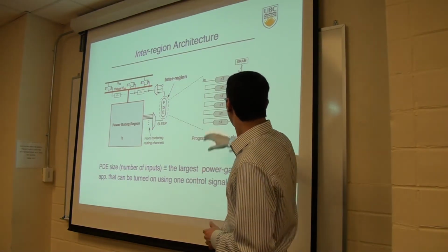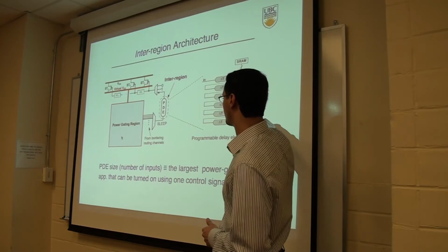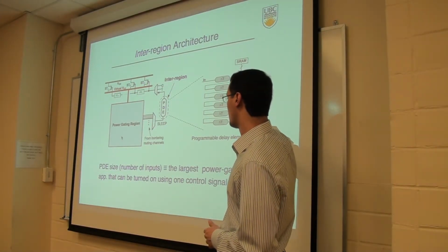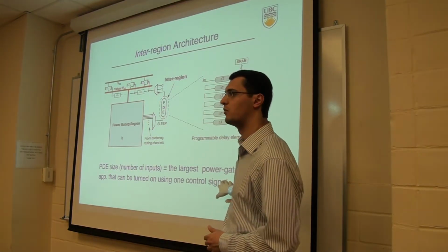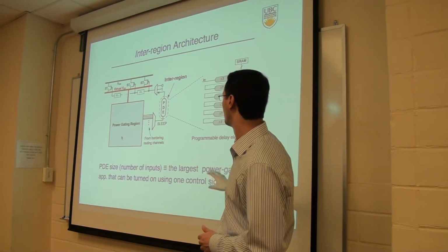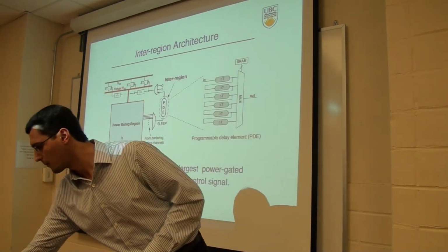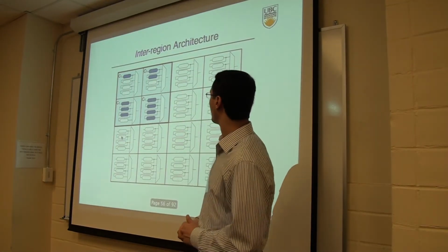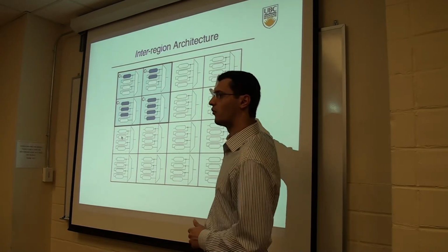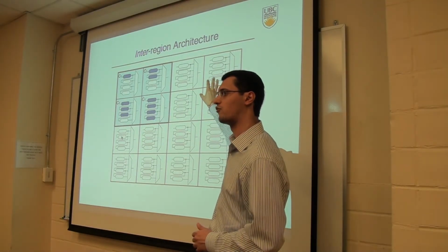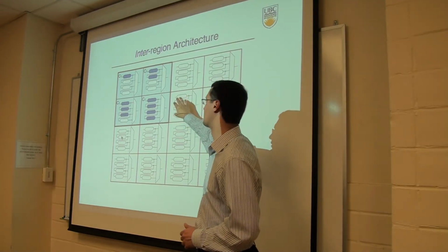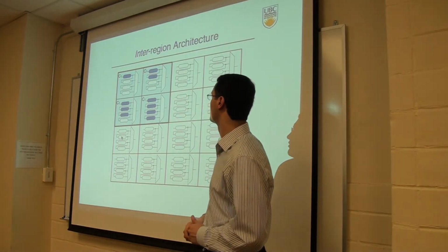One thing here is that the size of this multiplexer, or how many delays can be generated by this programmable delay element, is related to the largest power-gated application that can be power-gated by the same signal. And I will show you an example of what I mean by this. Here I'm showing an FPGA with power-gating regions of our architecture, and I represent each region using only the programmable delay element.